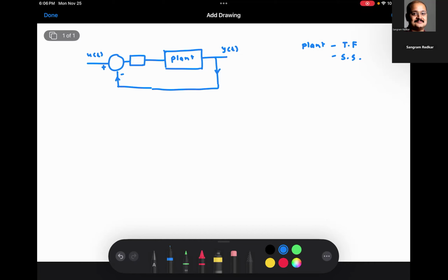And at the end, what you want is y of t divided by u of t close to 1. In terms of robot, you supply the signal so that your input is equivalent to 60 degrees of joint motion, which means at the end, the robot should move by 60 degrees.